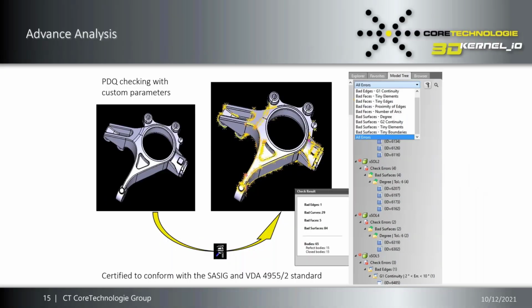And so those advanced tool capabilities will allow you to heal for a solid model, but go and understand the underlying math, understanding the G1, G2 continuity or any twisted surfaces in the background that would cause a big problem when you're creating NURBS in the CAE space versus the CAM space.